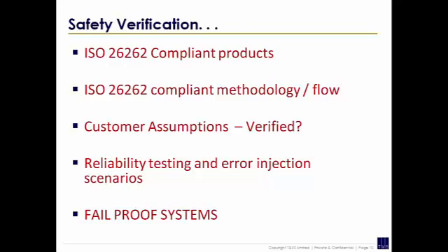So we usually go for ECC, error correction codes, and every bus has to have some ECC bits coming along for protection to make sure there is no error. And if there is an error, how many bits of error can be corrected? So this is a kind of negative verification. We inject errors purposely and see how they propagate. And we have dedicated blocks in the SoC which highlight that there was an error and go for correction. So basically we are looking for fail-proof systems.